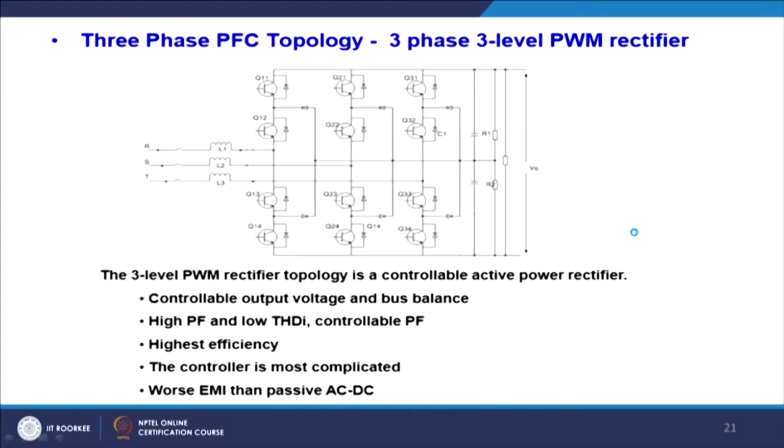And this is its multi-level version. I have shown the 3 phase 3 level diode clamp inverter for handling higher power capability. You can of course go for multi-level depending on its power rating. But the switch count becomes more, and this is one of the simplest multi-level inverters.